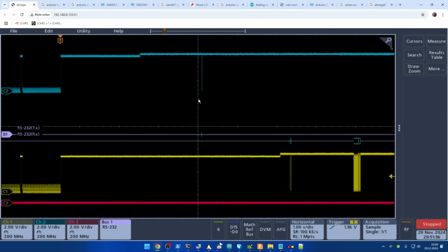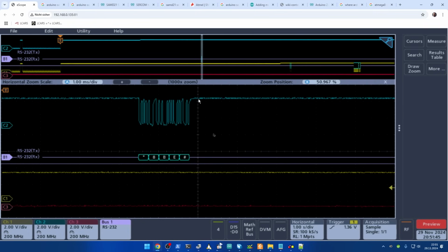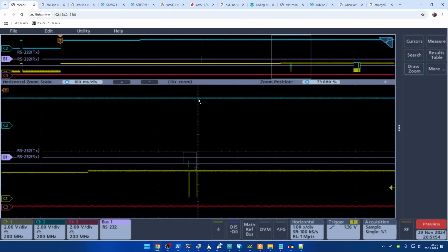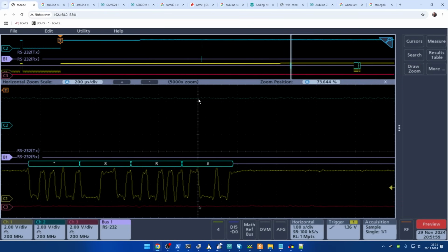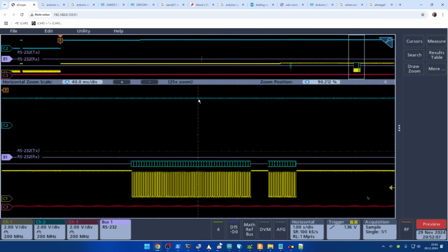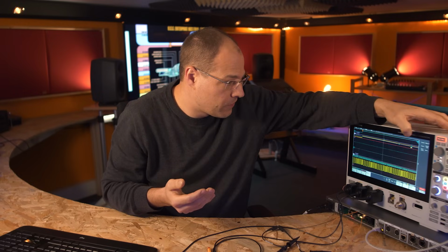Okay, and here we have some information. So zoom in to this. Okay, *8BE#, that's fine. That is what we are sending. And then the X32 is sending something: *8R#. Okay, it requests some information from us, but we are not sending. Why? And then what is here? Ah, the very long initialization command. Okay, the communication seems to work, but we are not answering.